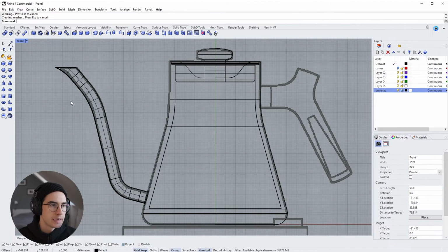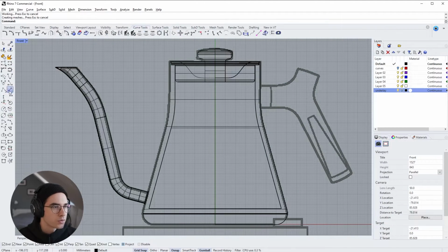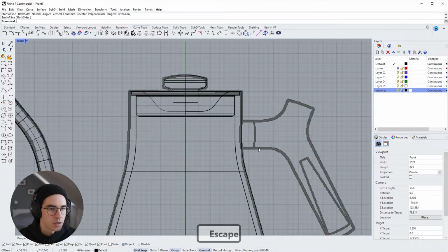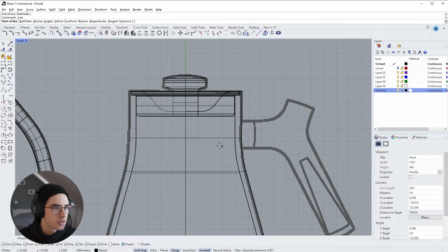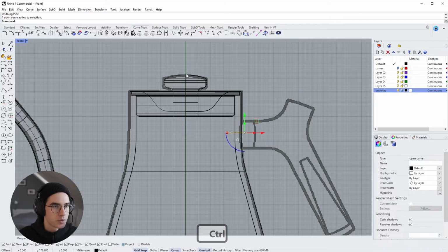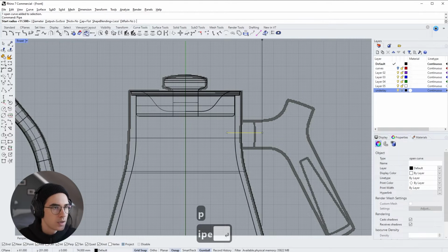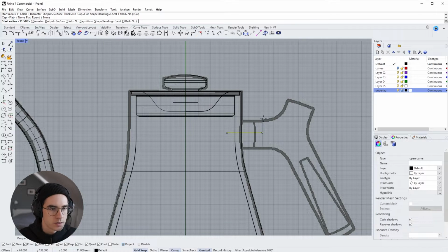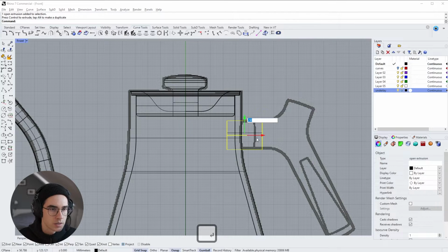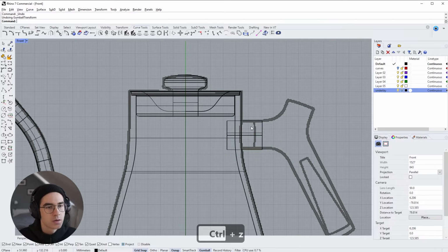We need to draw the main sketch. So I'm going to curve tools and just measure roughly how big the diameter is. I think it says 23 millimeters, so that's what we are going to use. Next, we can just create a single line, and there's many ways to do this, but I'm just creating one line. Now I'm using the pipe tool again, hit pipe, and make sure that the cap is off. We don't want a cap, we want an open cylinder, and type in 11.5 for the radius for both sides. Hit enter a few times in order to accept, and now this is our main cylinder.